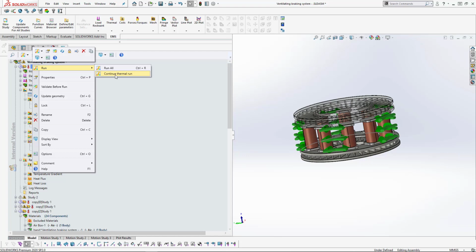We have the motion coupling and the thermal coupling, so you can get both dynamic and steady state results of your magnetic simulation. I mean the braking torque in a steady state, or the dynamic behavior of the braking torque. So you can get the braking time, and you can couple your magnetic simulation to thermal to get the heat generated in a specific time. That's all. Let's finish our presentation.